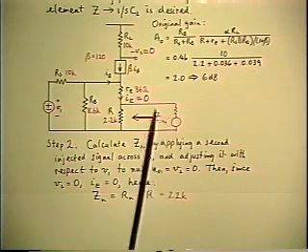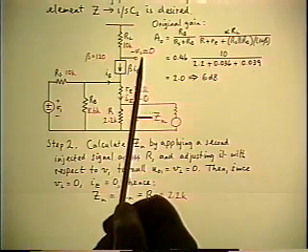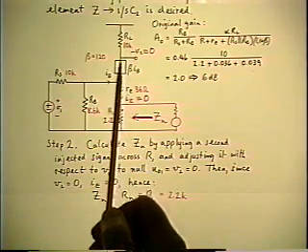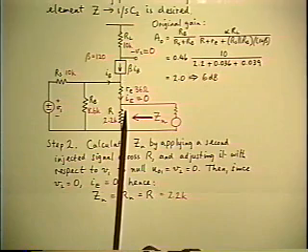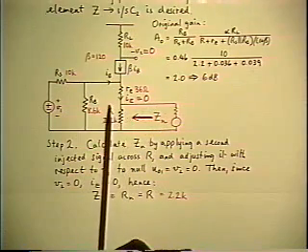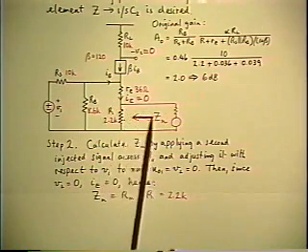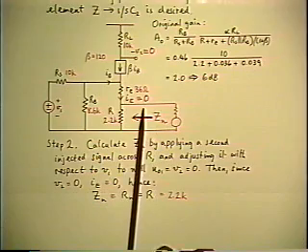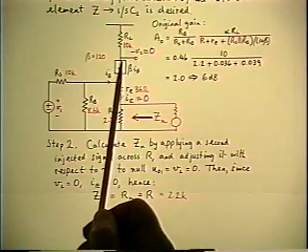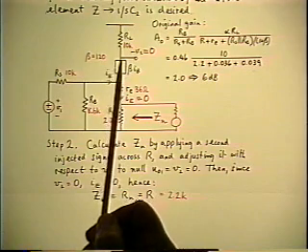The way you do it is you start with the null and you propagate the consequence of the null towards the second source. The purpose in doing that is you want to know what happens to the current going in from the second source. That's what enables you to calculate the Zn. So you start with the null, which is an established condition, and you make the following argument.